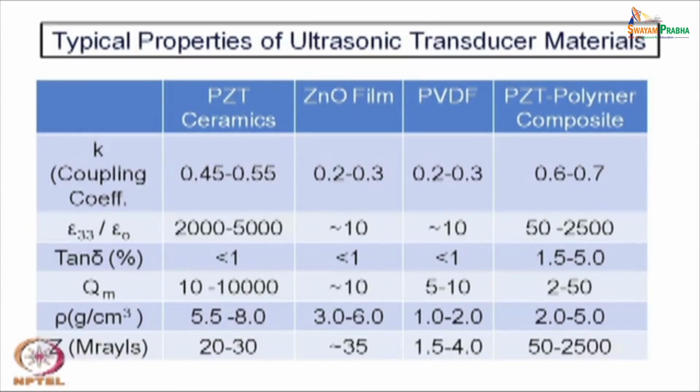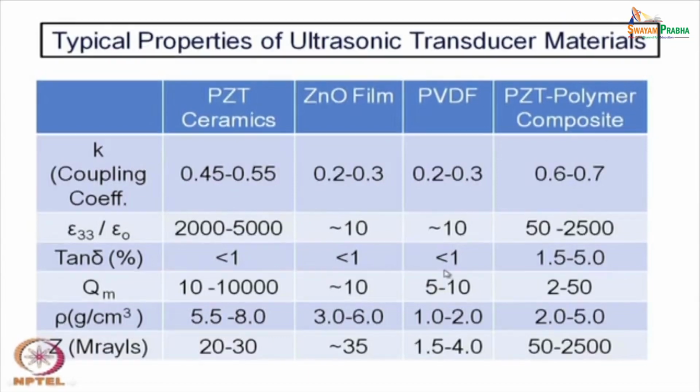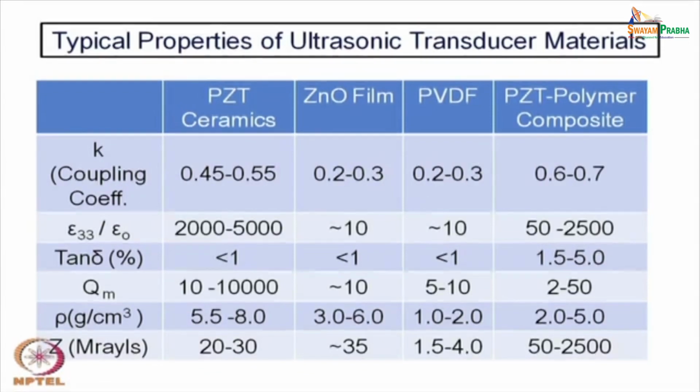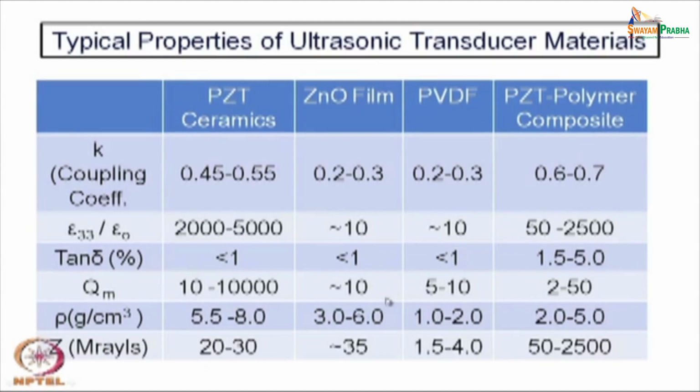This is one we mix. We have talked about PZT polymer composite, or ceramic polymer composite, for the piezoelectric materials. In such cases where you need a low impedance and low dielectric constant, you mix PZT with polymer. So, you make a polymer ceramic composite, and those are very important for medical diagnostics as well as some of the sonar applications.